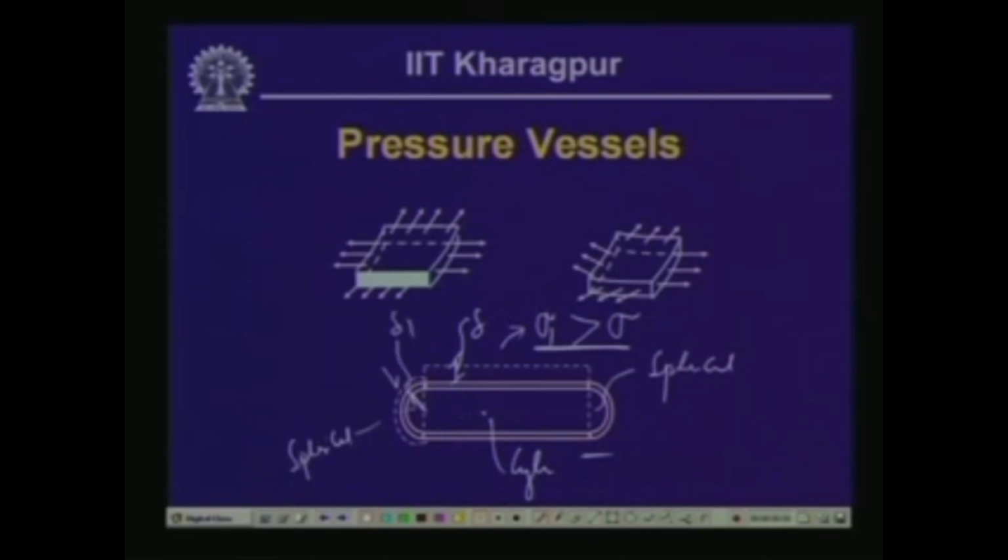Now, the problem arises at this particular junction, where the container is a combination of the end of the cylindrical part and the starting of the spherical part. At this junction, we have larger deformation from the cylindrical end and smaller deformation from the spherical end. So, as a result there is a mismatch in the deformation at that junction. So far as the whole assembly is concerned, there should be continuity of the element, and thereby some other kinds of stresses will be generated apart from the stresses that we are discussing over here.